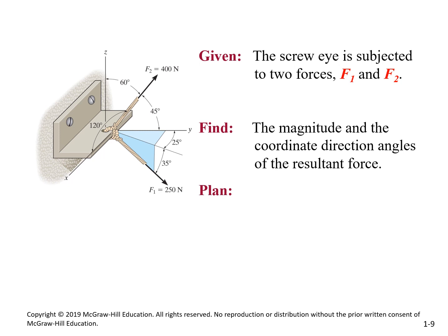The one with the z-axis, 60. How many projection angles do I have? 2. They are all for F1. Do you remember how we decompose each vector into its components, x, y, and z, i, j, k? So for the first one here, before I find the resultant between F1 and F2, I need to break each one of them into x, y, and z components.